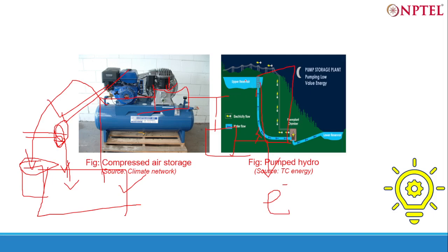So what happens is, from the upper reservoir that is located at a very high head, we take the water and pass it through the turbine. After passing it through the turbine, we don't let the water go into the river. We store the water in a lower reservoir. Okay, maybe some water can go to the river because we have to maintain the continuity of the river also.